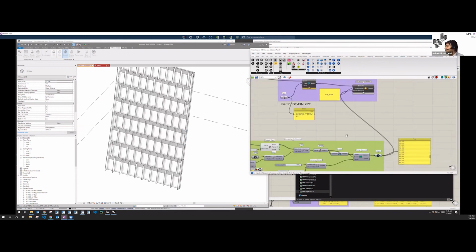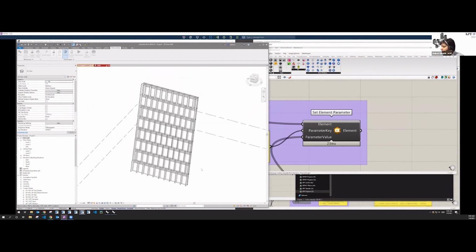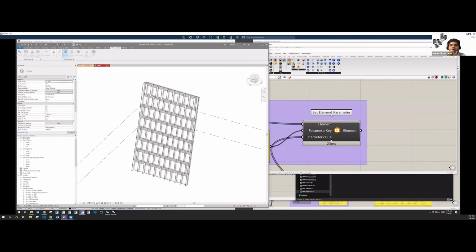So yeah, that's pretty much it on how you can place fins and a more complicated adaptive panel inside of Rhino.Inside using Grasshopper. It should also be noted that this is a pretty small example. So if you want to start playing around with sliders inside Grasshopper and it's a big facade, definitely look at freezing the creation of the Revit geometry. As you update the sliders, it's recreating all the instances every time you update.